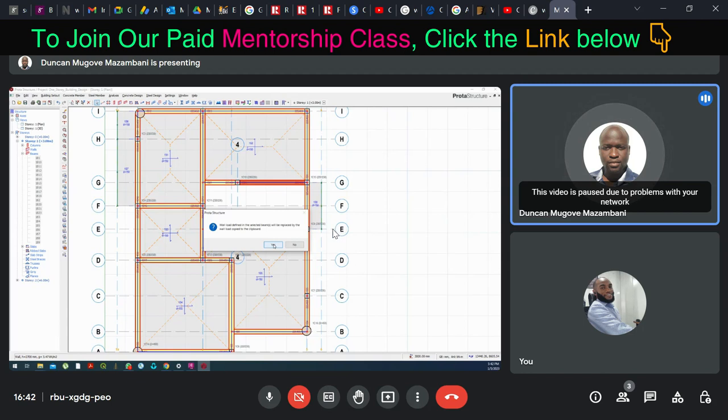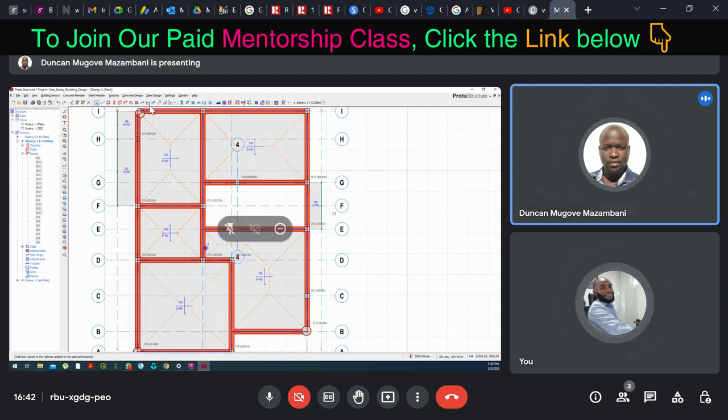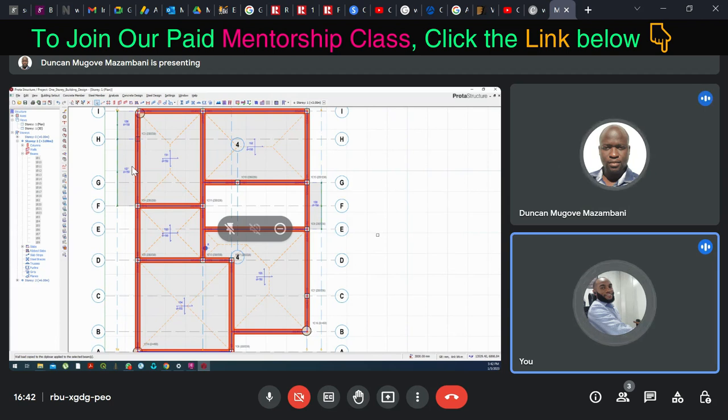The wall load defined for the selected beam will be placed. Say yes. Click on yes. Now on the place where you have cantilever edges, click on those beams and remove the beam wall load on that area, because we have already transferred the wall load on the cantilever edge. So the place where you have cantilever, click on it and remove the wall load.